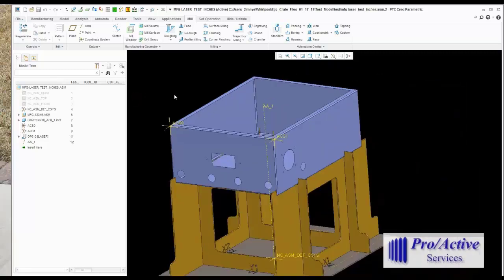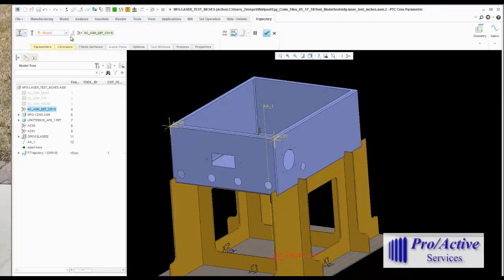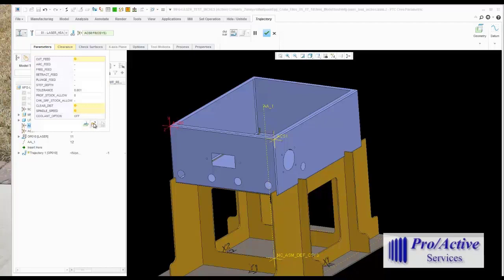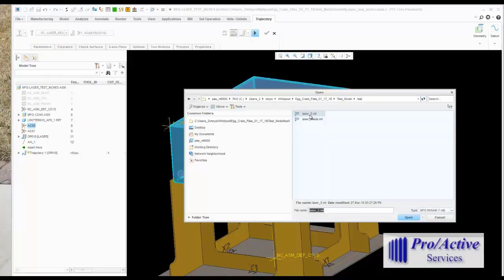What I have set up is the operation program 0, which I have set down here in the base, center of the part. You can position that wherever you'd like to. So I'm going to start by creating my first cut. I'm going to create what we call a trajectory sequence. I'm going to pick the tool. I'm going to pick a coordinate system for tool orientation. I'm going to select parameters, things like speed, amount of stock, and so on.